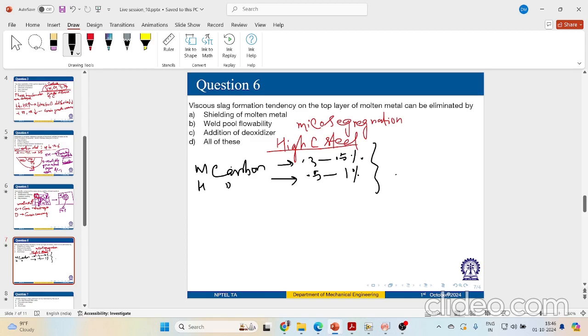But in a similar way, there will be these three regions: partially refined region, grain refined region, and grain coarsening region. Now, in the grain coarsening region, position D, both high cooling rate and large grain size will promote the formation of martensite.